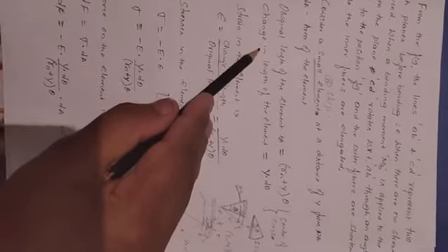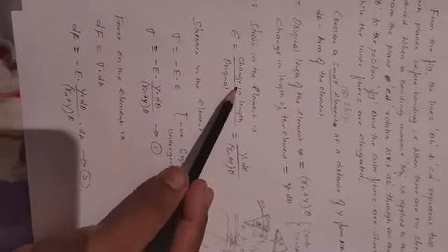Once you apply an external bending moment on the right side, in the counterclockwise direction, there is a change in length of the element, a decrease in dimension. How much does it decrease? You can see from here to here it is y, that is a radius. The angle is d theta. What is the arc of the circle here? y into d theta. This is the change in length of the element. As you know, the strain induced in the element is the change in dimension to the original dimension, here the change in length by original length. This is the formula you will get.